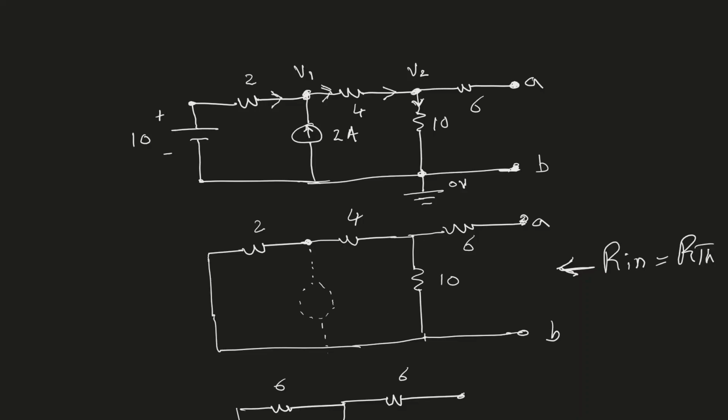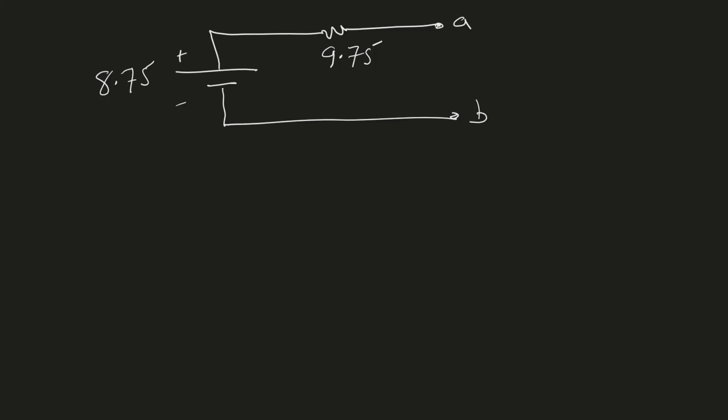So we want to show that. So for that, we will now consider any value of the load resistor. We can assume any value, and we will then solve both circuits to see if we really get the same values for voltage and currents. So now let's test these two circuits. And let us assume that the load resistor is 1 ohm.